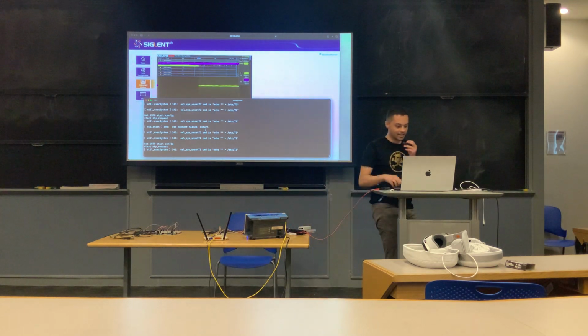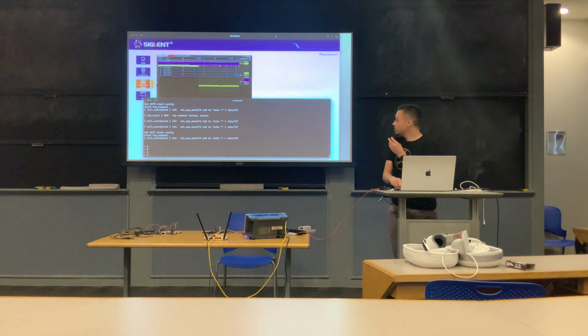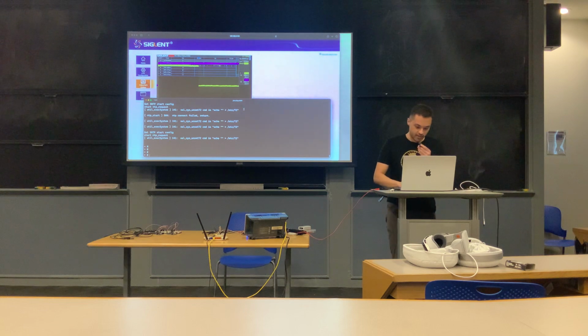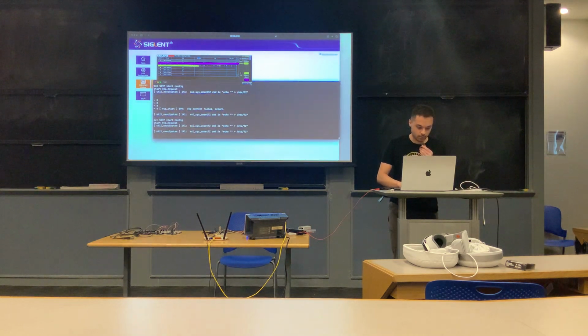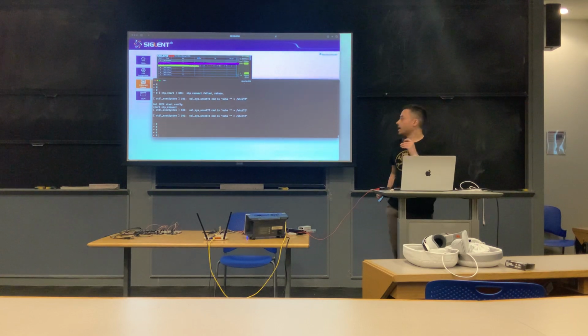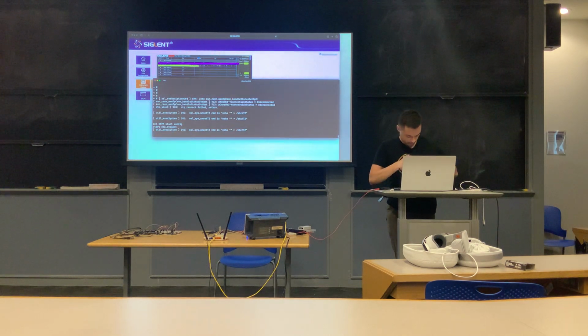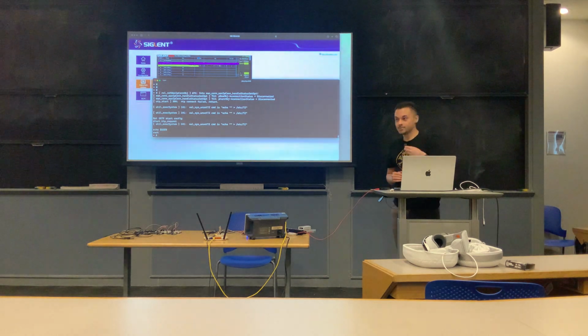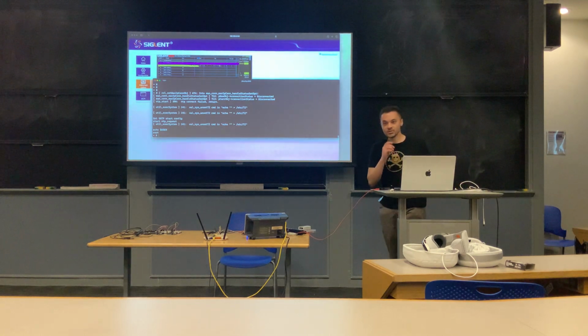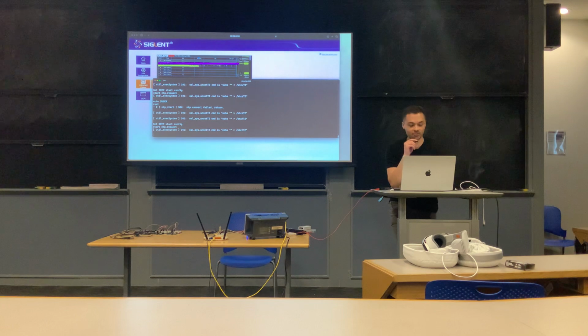If we go ahead and try to send some data here, you can actually see we're observing transactions on the bus. And so we're able to actually input data and observe the contents over the serial port. But now let's see, what are we actually looking at here? So whenever I press enter, I can see a little shell sign. What does this remind you guys of? This looks to me like a shell. And so if I go ahead and type something like echo user, oh, I'm the root user. That's pretty interesting. So it seems like this router is just giving us a root shell completely for free.